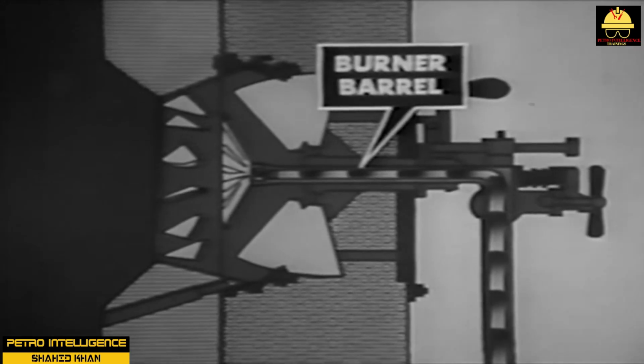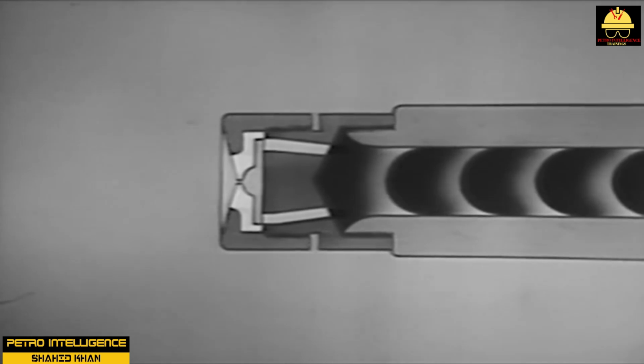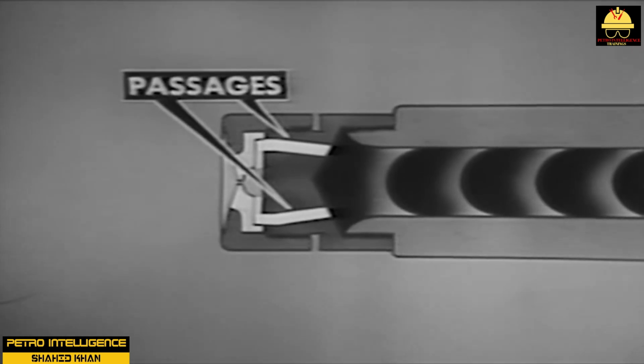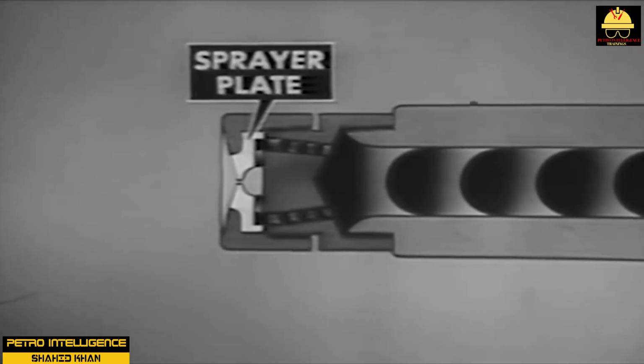Air shutters on the burners control primary airflow into the furnace. Air registers near the burner control secondary airflow. These registers normally are closed when excess oxygen is detected in the furnace. The single burner in this system is a low nitrogen oxide system located on the floor of the furnace.